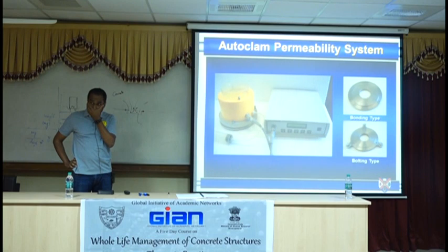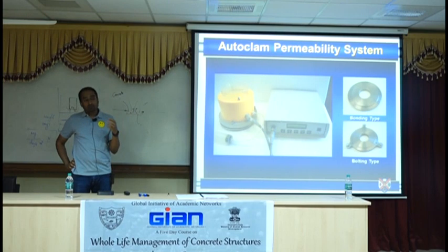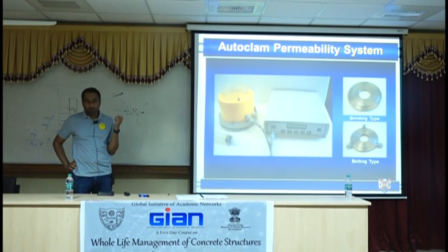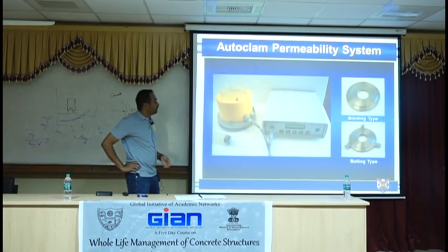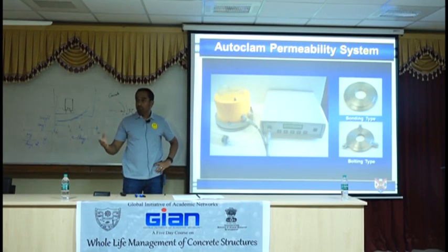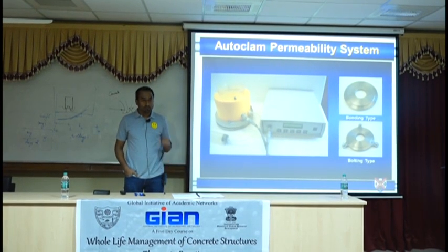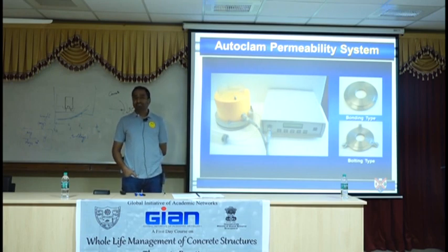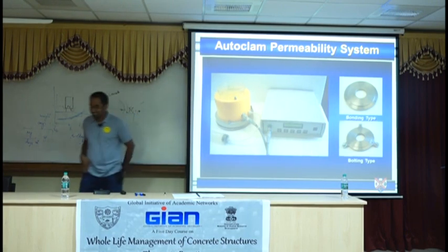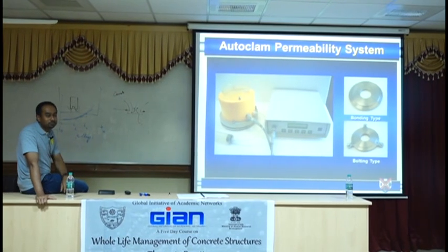Creating the same environment. You're testing on the surface. Surface will have different environments. If the environment is moist, above 80%, it won't work. It can't work because you can't compress water. So you'll have to dry the surface if it's more than 80% humidity, or you'll need to find a different way of testing it. That's the first limitation. What's the next limitation? By the time I've listed all the limitations, you will actually develop your own test anyway. That's the idea. I'm a researcher, I'm not a salesperson. Go ahead. What's the other one?